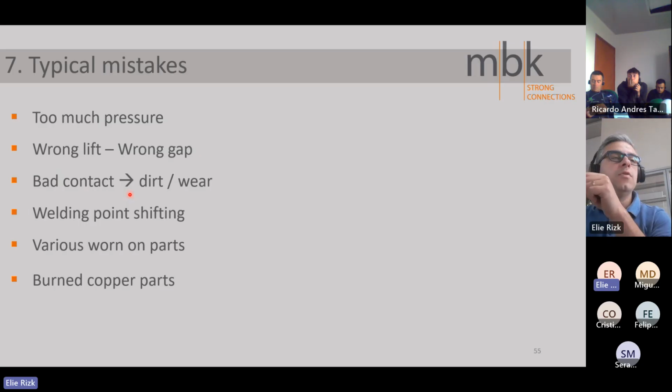It's better to clean the welding angle, and also the spokes where the sliders move, because sometimes dirt will accumulate there, and then you have some problems with the sliders. They don't move freely, they are too tight, or they are scratched. So they scratch the plastic isolation between the slider and the spoke, and then you can have some problems.